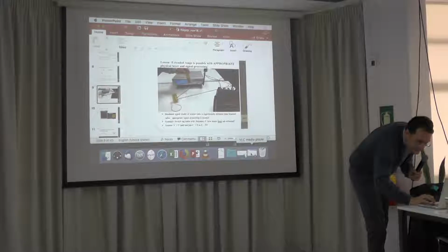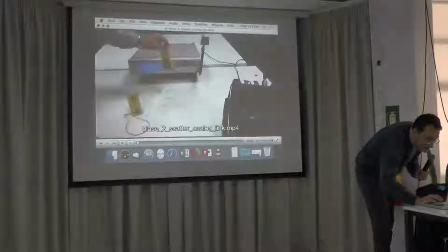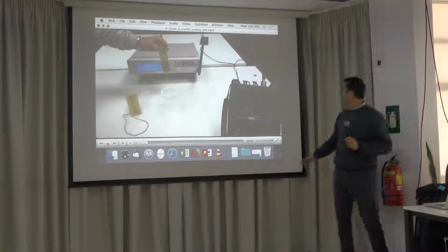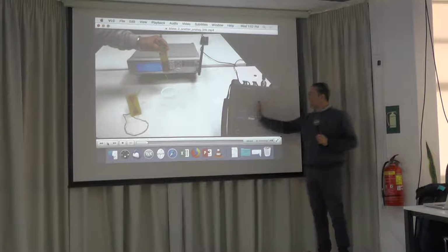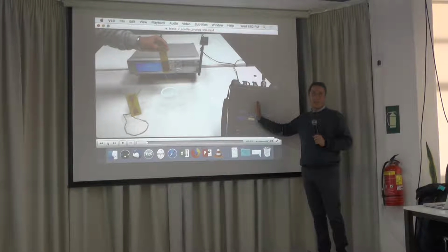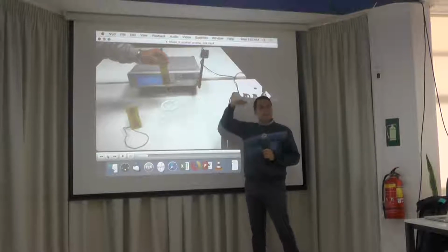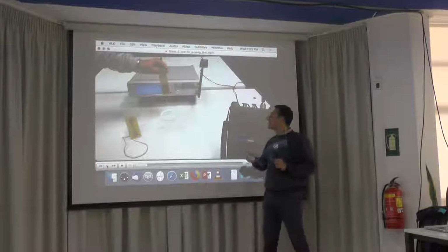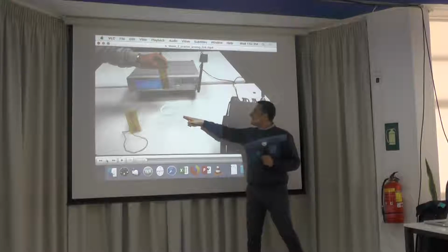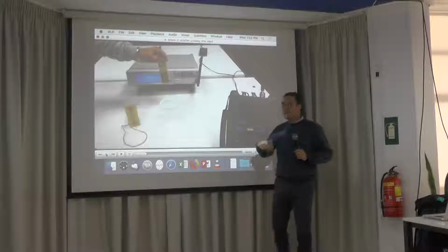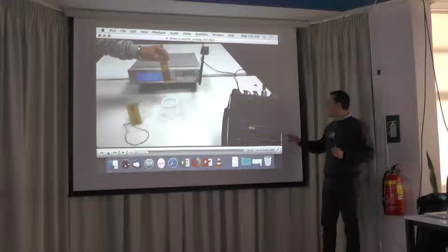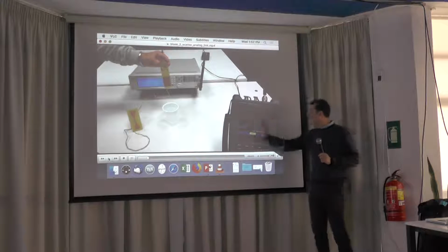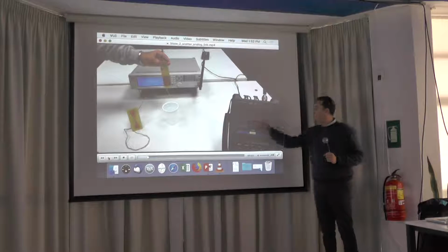Sorry about that. Okay. So can you see the two peaks? I have 868 megahertz, which is basically a tone, a carrier, a cosine that I showed you before. So this is this peak. And I'm switching this antenna between two loads with a frequency of 30 kilohertz. So here I have two peaks, one at plus 30 kilohertz and another at minus 30 kilohertz, around that carrier tone. And you can see the two peaks here.